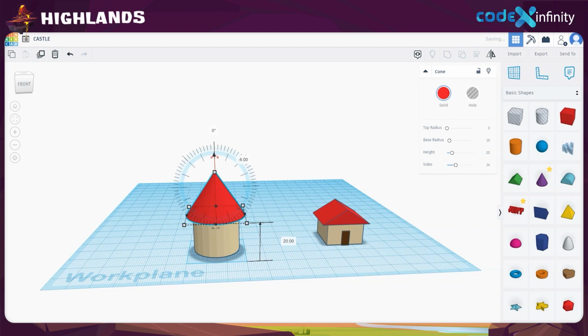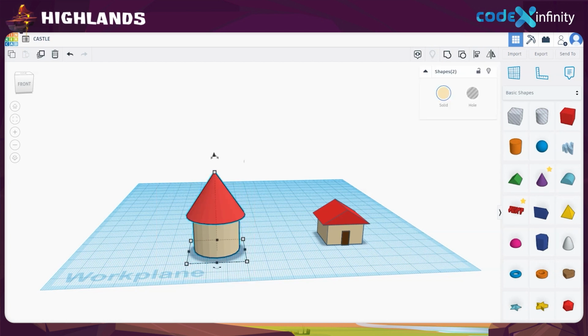Now, to make the alignment precise, we want to use the Align tool. So select the tower structure completely by dragging the mouse. Then move the cursor to the toolbar and click on the Align tool, or simply press the L button. The black dot-like structures have appeared around the tower. And if you look at it, we can see the black dot at the center of the front portion is blurred. So that means the alignment in the front portion is exact. And if the dots are not blurred, just click on the dot at the center to get it aligned perfectly.